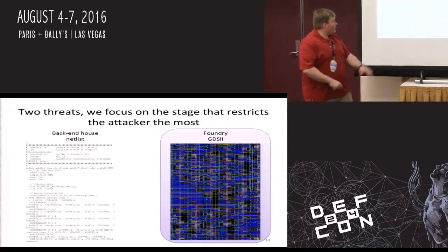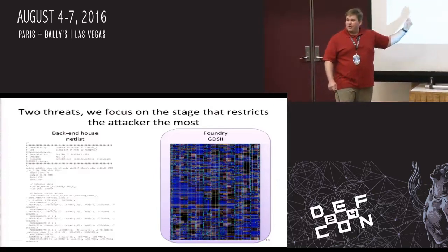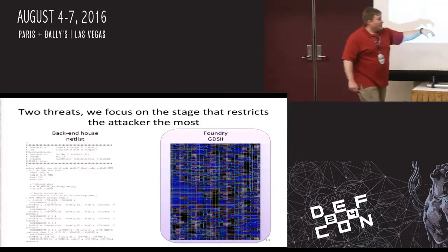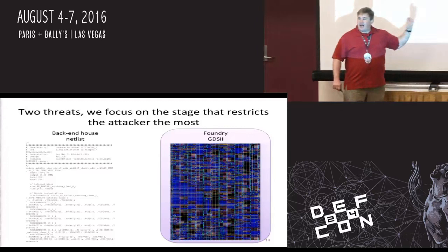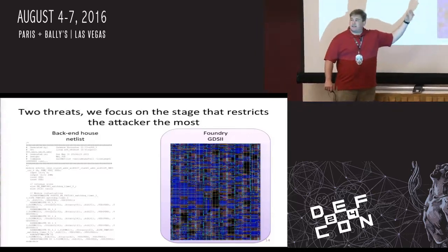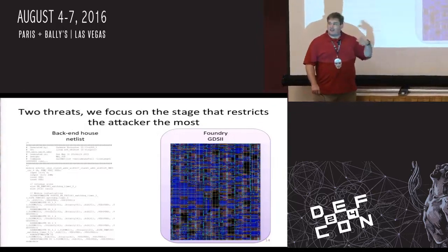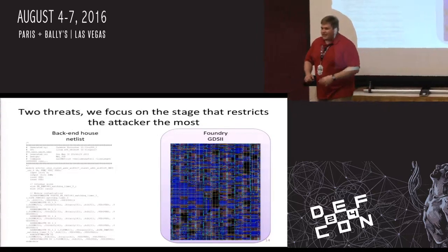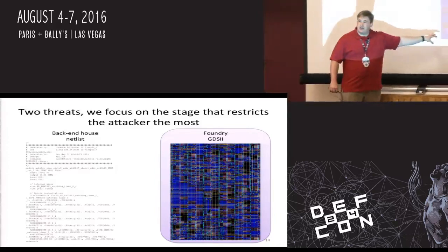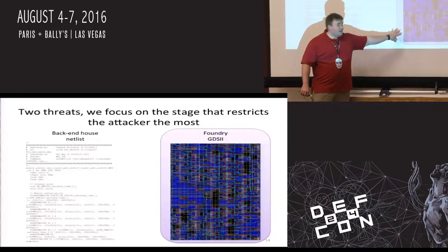This is what a netlist looks like. It's still just a text file. It's less human readable, but an important point is it does have meaningful names. If you go down a little lower, if you were actually to build it, place and route your design yourself, you could hand TSMC this art-looking thing here, which is just a visual representation of polygons that represent wires connected together. This is called a GDS2 file, and this could be fabricated directly. And we're going to focus on this.